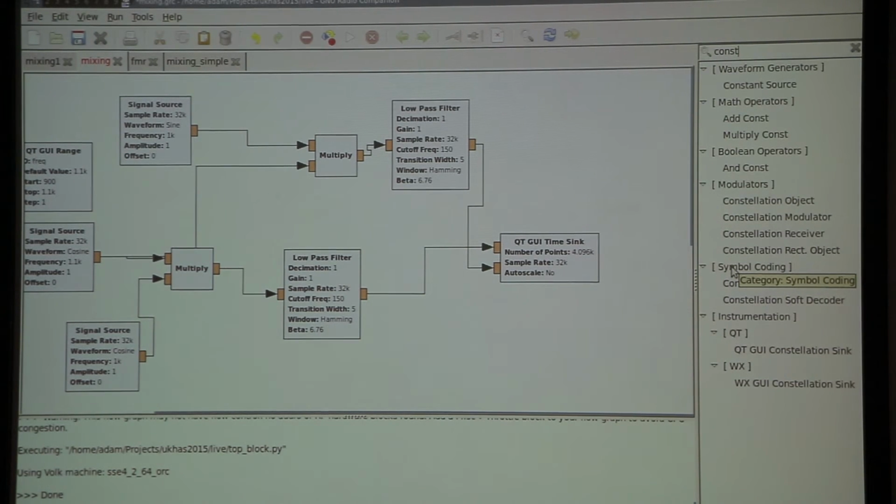Yes, I understand that, but what's commanding it to change frequency? What commands the signal to change? Yeah. Well, whatever is generating the radio wave. So typically, this will be like a microprocessor on your balloon, sending a voltage high or low into a radio module, which then changes between two frequencies. Okay. And then that's what we're interested in receiving. In the HAB case, we want to know which frequency it is currently running at.